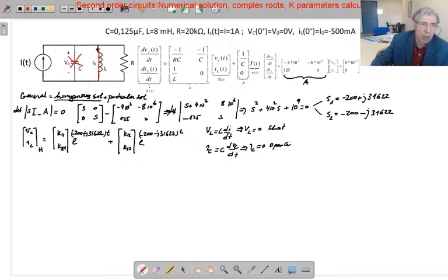Voltage is 0. Since these R and L elements are connected in parallel, resistor voltage is also 0. By definition, resistor's current is also 0, so that's going to be open circuit as well. So in this case, this independent source current passes through this inductor. Inductor current, that is particular solution, is going to be equal to that source.